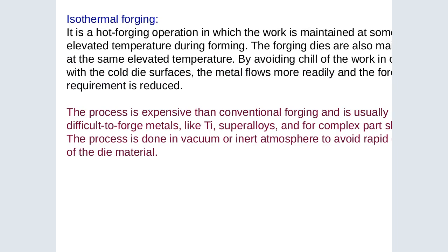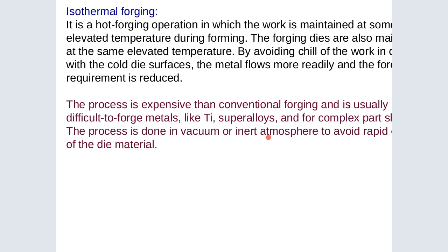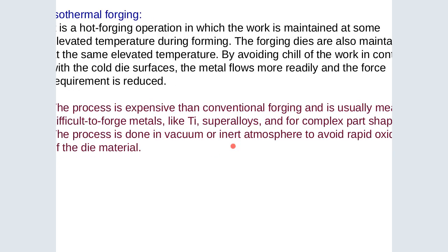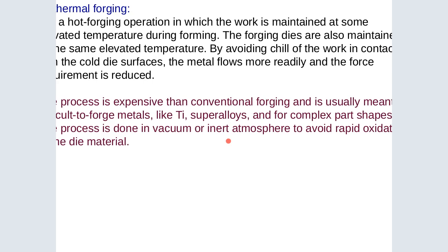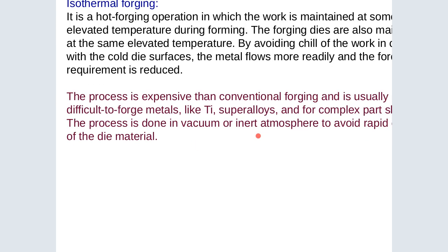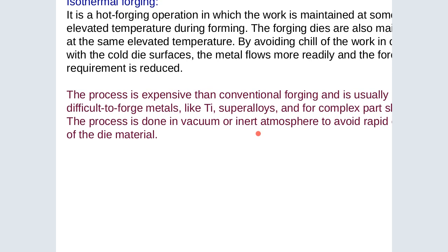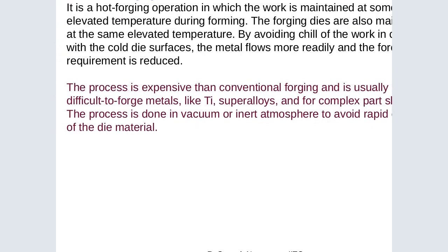Isothermal forging. It is a hot forging operation in which the work is maintained at some elevated temperature during forming. The forging dies are also maintained at the same elevated temperature. By avoiding chill of the work in contact with the cold die surfaces, the metal flows more readily and the force requirement is reduced.